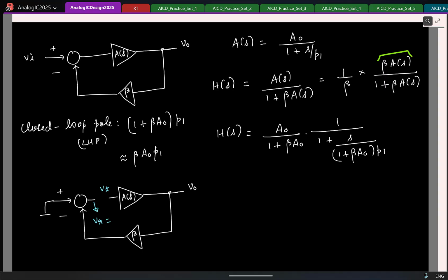Can you check carefully? Minus? Okay. Yeah, sorry, into Vt. So this ratio, the negative of the return voltage to the applied test voltage, is what we define as the loop gain, because that is the gain you have when you actually go around the loop completely.